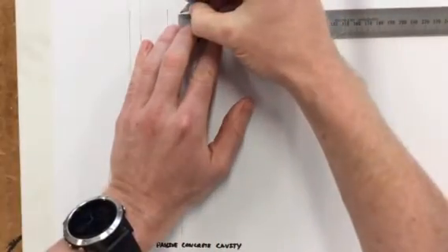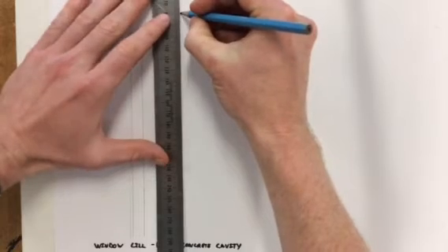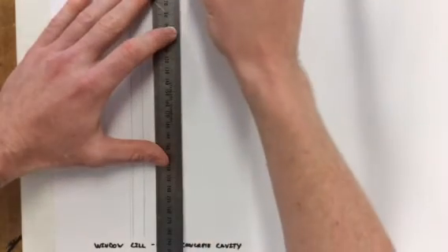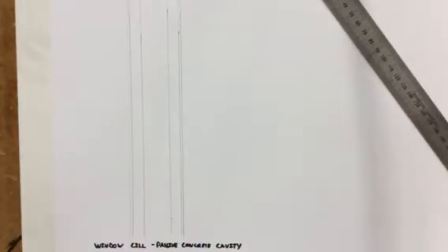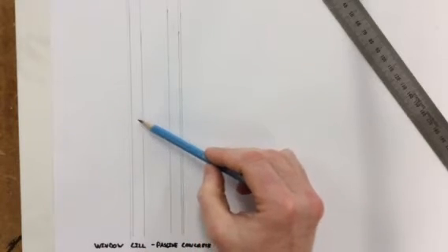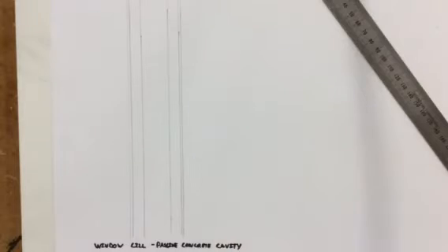Again, I'm just going to mark it off as 2mm on this, because we're doing the drawing at scale 1:10. Now this might look a little bit easier to follow: render, blocks, insulation, blocks, internal plaster.